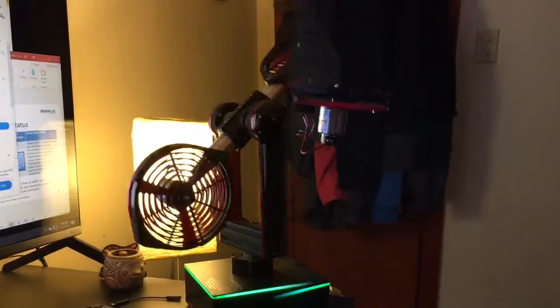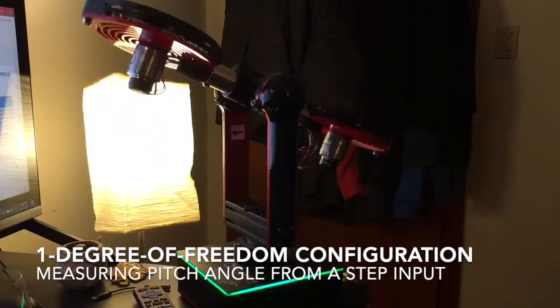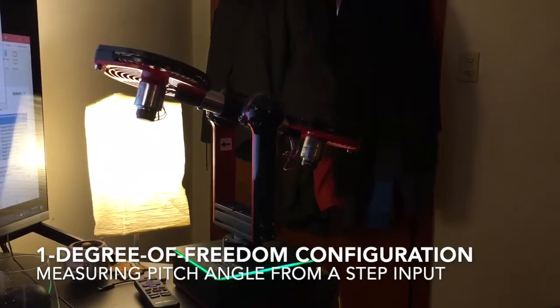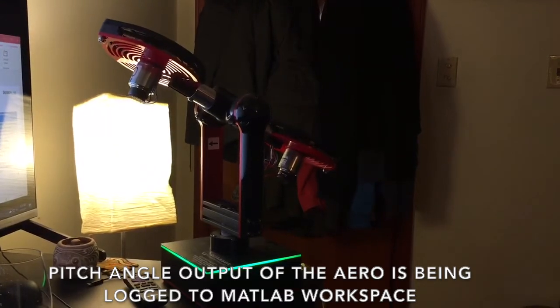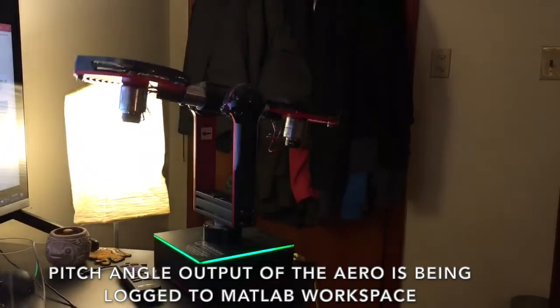Here, the Aero is in its 1 degree of freedom configuration, with a 24-volt step input applied to only one of the motors for 20 seconds, and then that input is removed for an additional 20 seconds. The pitch angle is being measured and recorded to the MATLAB workspace for analysis, and to evaluate several models that were developed of the Aero.